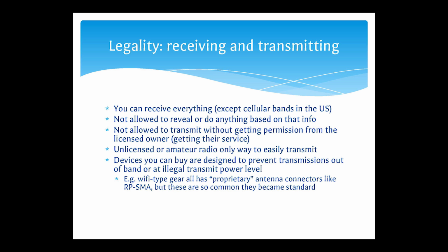So the FCC's idea of putting non-standard connectors on your radio so that no Joe Schmo on the street can just plug in a high power antenna and transmit at illegally high power levels didn't work as planned. Also, you can get connector adapter kits. I got a nice one for about $200, which is a pack this big of every standard RF connector with little twist-on connectors, so you can connect anyone to anyone else. So you've got lots of options like that for connectivity.